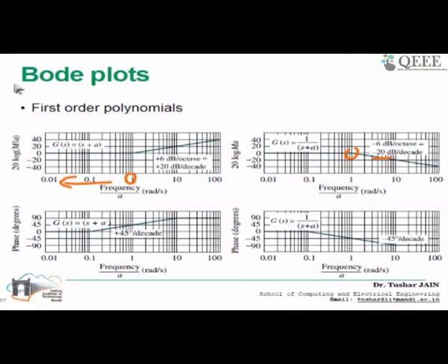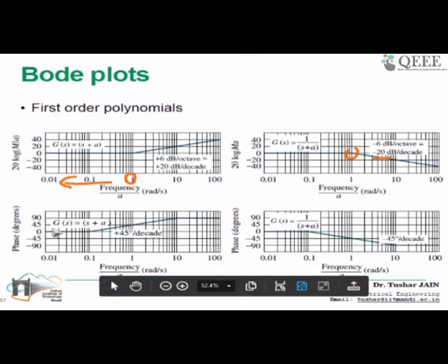We'll take the questions in the chat or in the question window after we finish this basic concept of frequency response. So now, if I have a zero at minus a, this makes a contribution of 45 degrees per decade, and this makes a minus 45 degrees per decade if I have a pole at minus a.